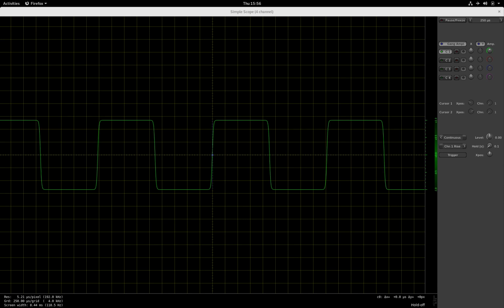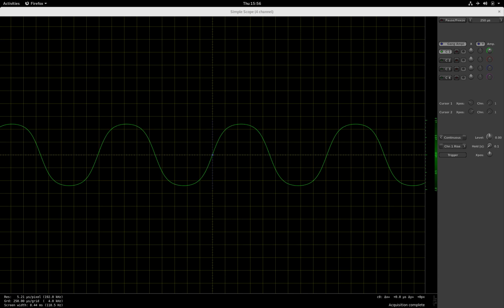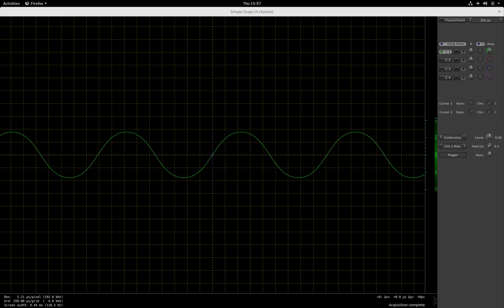Or I can demonstrate this again. If we reduce the gain, this is how the signal behaves. So it gets less squashed towards the supply voltage, and the slope through the origin will also decrease.